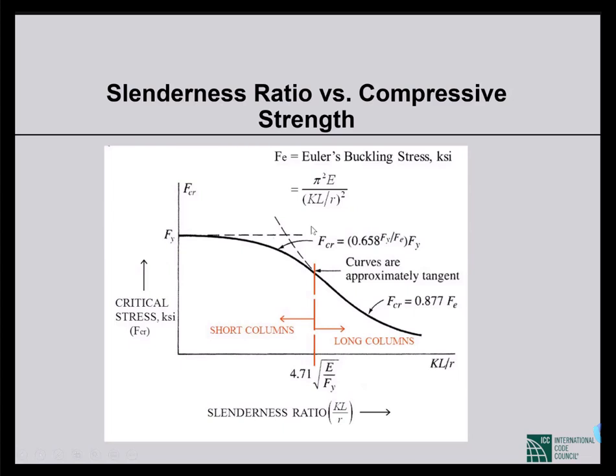So this curve, the formula is complicated for that one. This actually refers to the inelastic buckling, that some part of the section will go beyond elastic limit, and in the inelastic stage there will be buckling. So this is inelastic buckling stage that may happen for short columns. So this F here refers to that stage. So that's why we have two distinct formula.